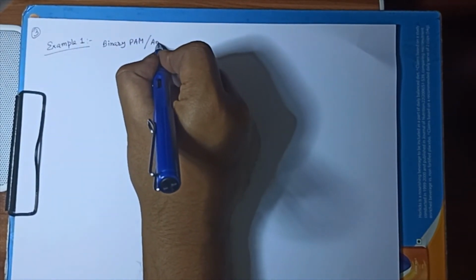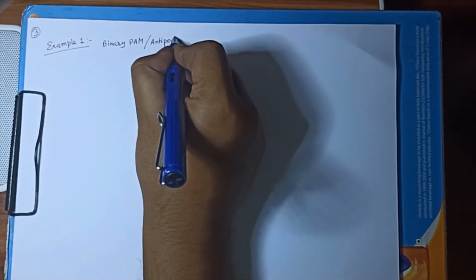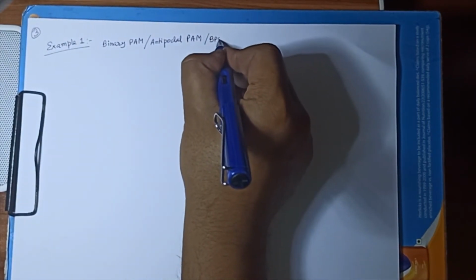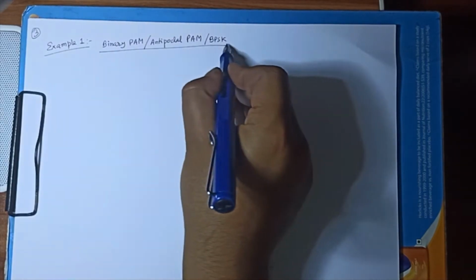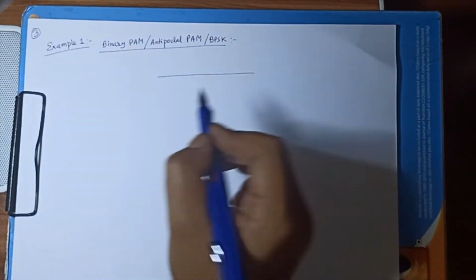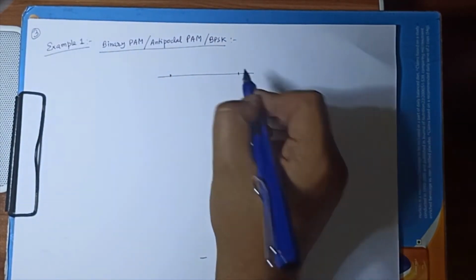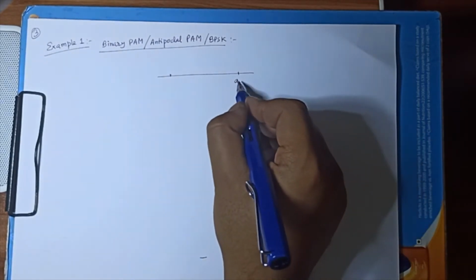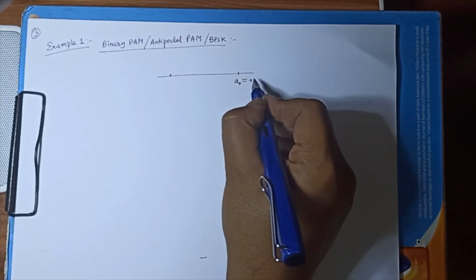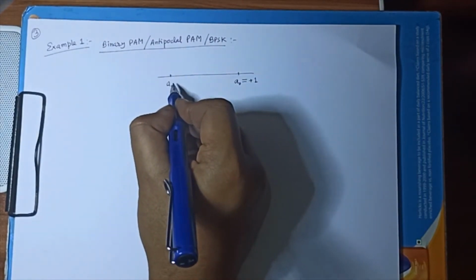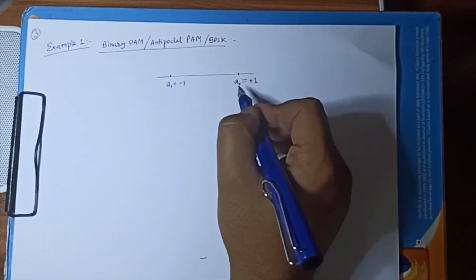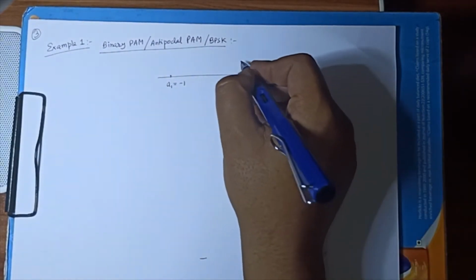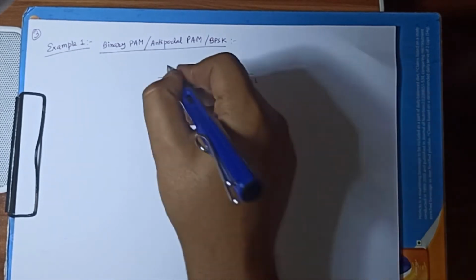There are different names, or it can be said BPSK also, binary phase shift keying, the same thing. So our observation sets are essentially these. So this is say A0. I am writing A0 is equal to say +1, and this is say A1, which is say -1. So symbol 0 is mapped to +1, symbol 1 is mapped to -1, and they are having the probabilities. This is say P0 and this is say P1.